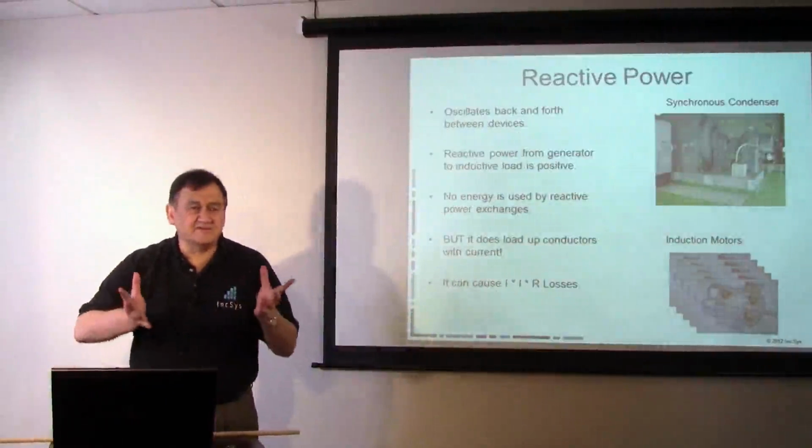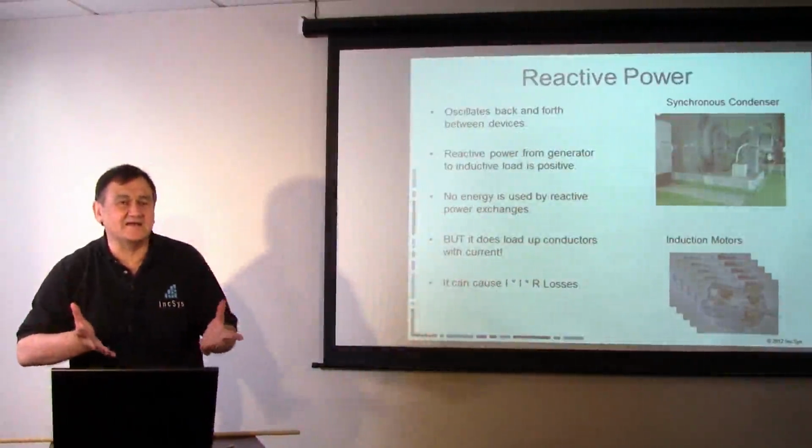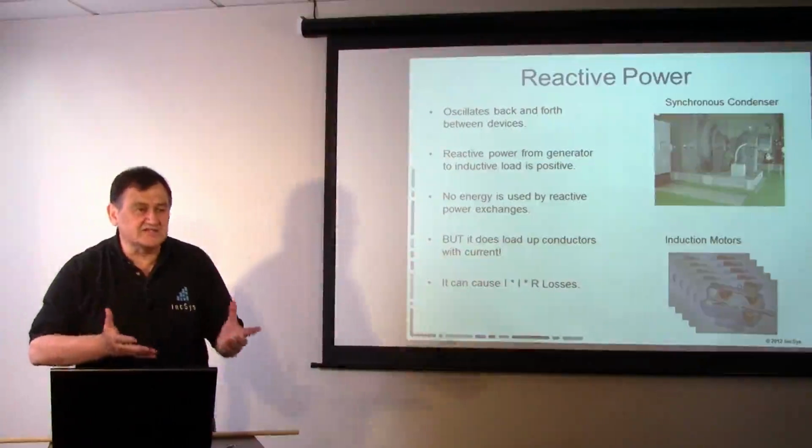With reactive power, it's totally different. It's a much harder quantity to really understand and visualize. We've had examples where people have commissioned their SCADA and state estimator systems, and they'll find many cases where the actual megavar flows are reversed.